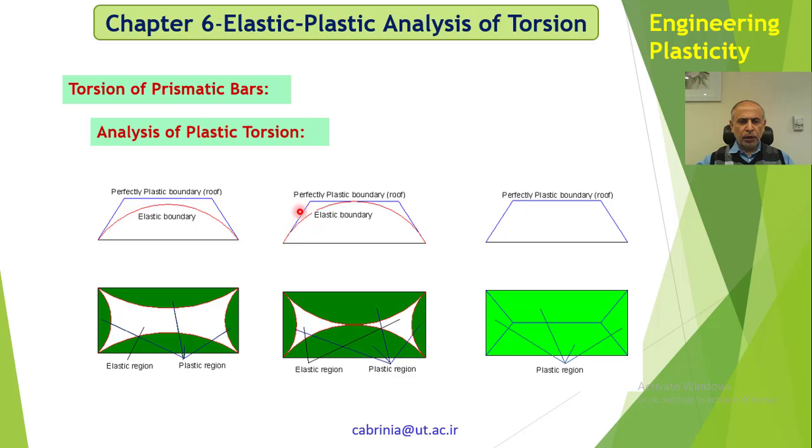Now, if we forget about this roof and just have a look at this membrane, as you increase the pressure, this membrane can bulge as much as you increase the pressure. But there is a limit for it. Where is the limit? If that gradient, which is the stress, reaches the yield strength, that is the limit. Okay? So that's what we have done.